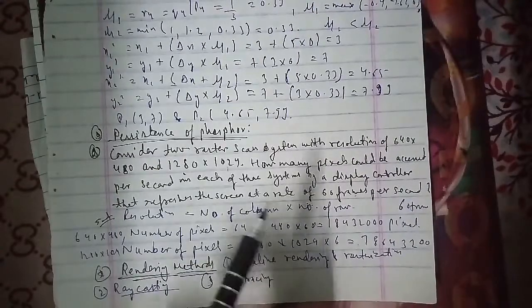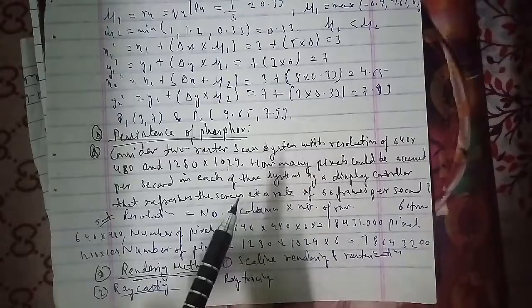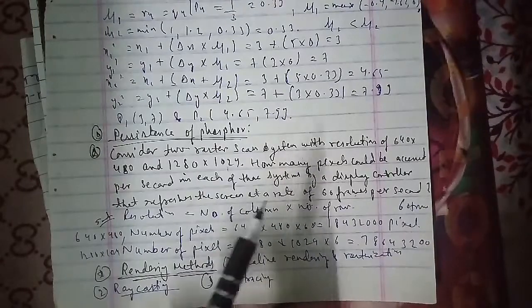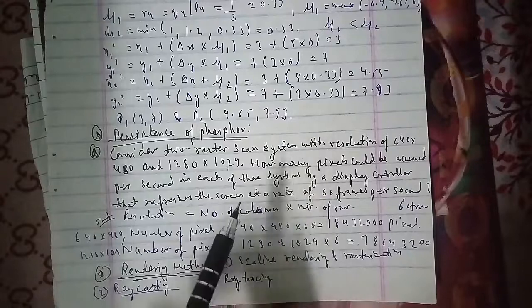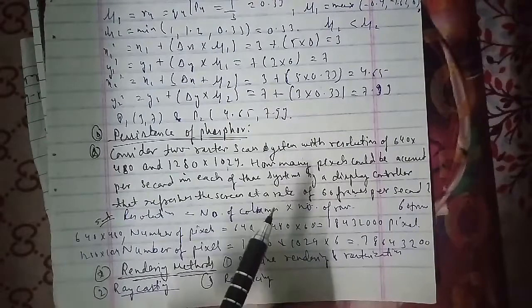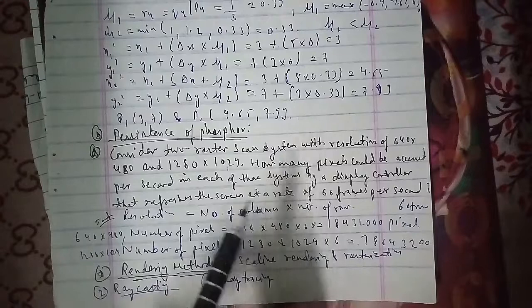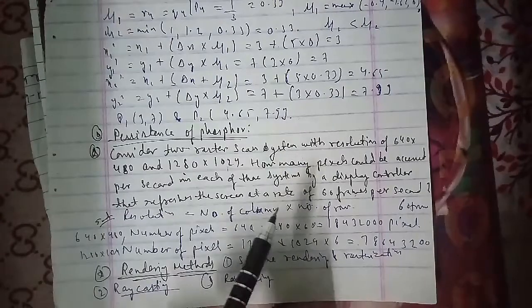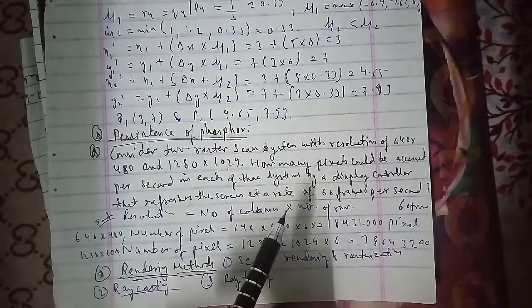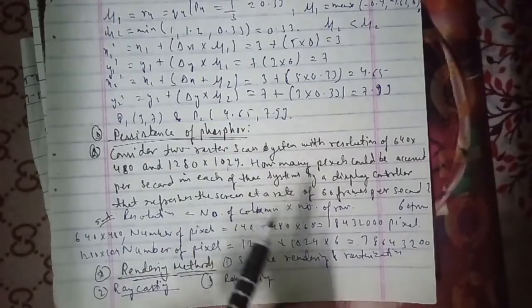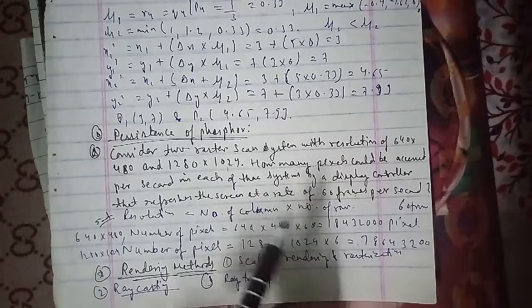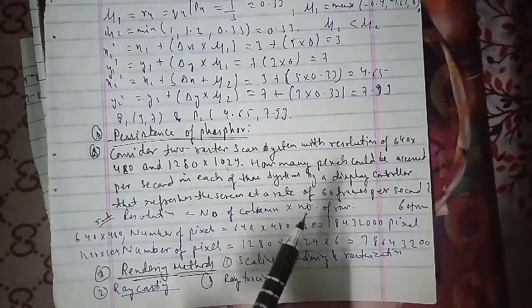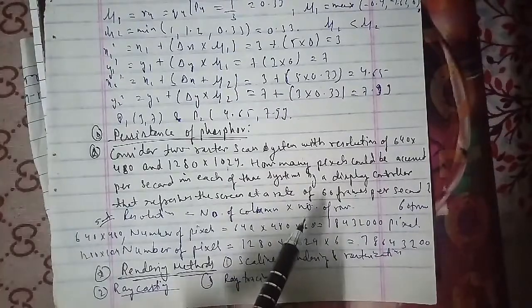In B-spline, the B-spline allows the order of the basis functions, and hence the degree of the resulting curve, to be independent of the number of vertices. In Bezier, the degree of the polynomial defining the curve segment is 1 less than the number of defining polygon points. And in the third, B-spline possesses a high degree of smoothness at places where the polynomial pieces connect. So these were the 4 differences that we talked about.